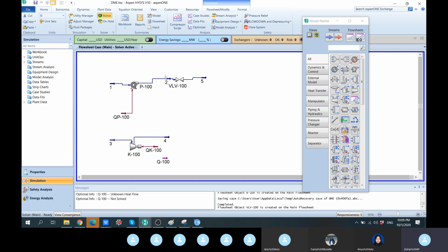If this is, for example, 262.2 kilomole per hour, then this is also 262.2, and this also has to be 262.2. The same goes with this 2.171. There are no reactions whatsoever, so the mole balance equals the mass balance. So in this particular case, it is a steady-state mass balance.